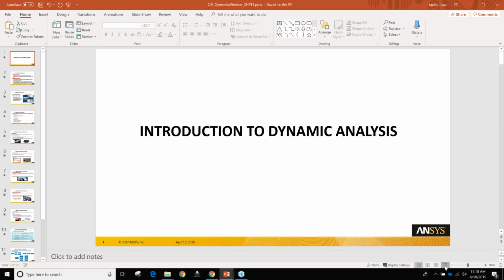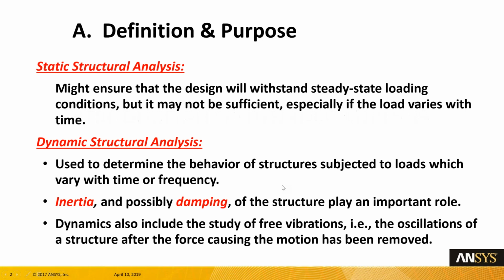the introduction to dynamics. So as we have seen, static structural analysis will do just steady-state load conditions. However, dynamic structural analysis is going to take into account inertia and damping. So if inertia and damping are important, then we have to do a dynamic structural analysis.